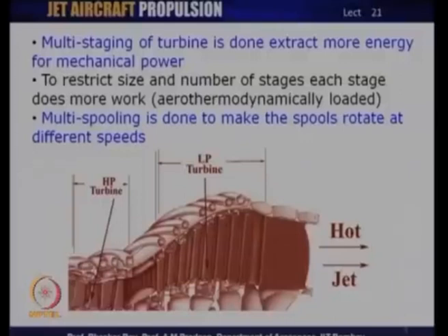The loading essentially refers to the amount of work that it can do in a single stage across one row of rotor, let us say, and that is signified by the aerothermodynamic loading, which means that a typical aircraft gas turbine is much more aerothermodynamically loaded compared to any other kind of turbine or gas turbine, which may be used in land based applications, where the restriction of size and weight does not quite apply so stringently.